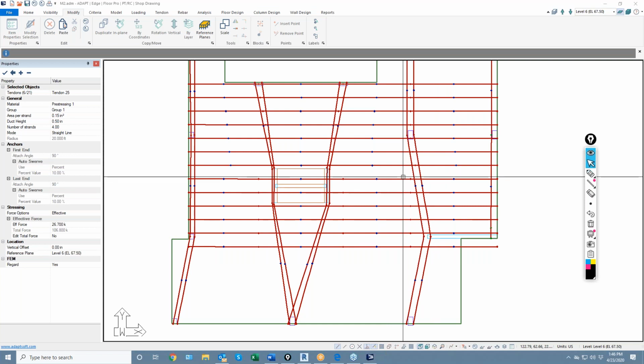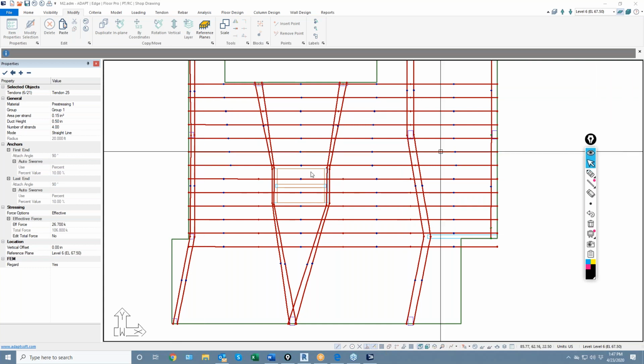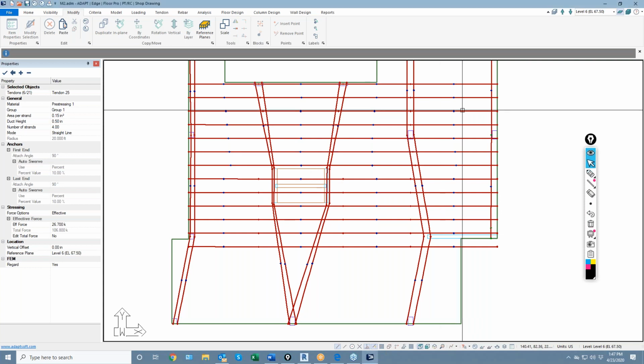That's more of an in-depth conversation, but in general, if the end bay condition is unrestrained, then you typically have to have more fire rating or safety for the tendons. So the end span would become, instead of 1 inch for the CG, we might actually use 1.75 inches per code for the CGS. So that could be adjusted.